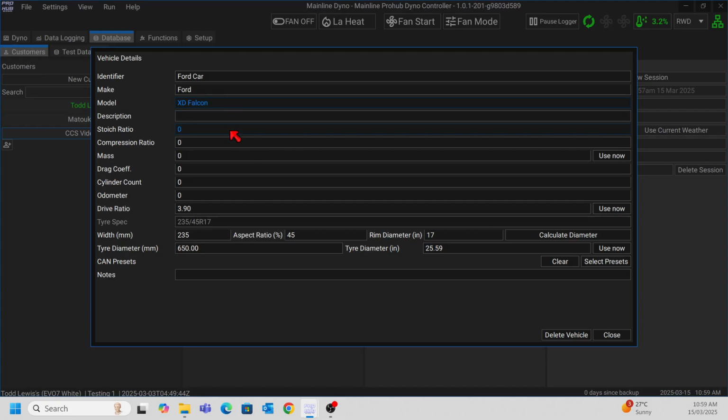The more important stuff is down the bottom here, where you'll notice there's always a default drive ratio. What we've done in the CCS system is to stop users forgetting to put a derived RPM figure in. For example, in a Dynlog system, it ultimately ends up with 0 derived RPM and other questions it always generates. We have a default ratio that always is applied. So there'll always be a derived RPM value. It may not be correct, but at least it'll generate the question. But it's a simple answer: you haven't set the drive ratio.